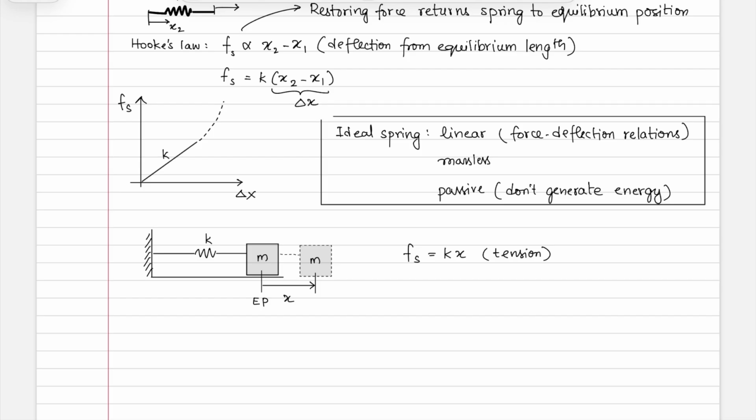If you were to draw now the free body diagrams of the different components of the system, I highly recommend doing it as an exploded view so you have everything available. This mass m is here and this here is a spring k. This is going to be in tension, which means that this Fs is acting in both directions as shown here.